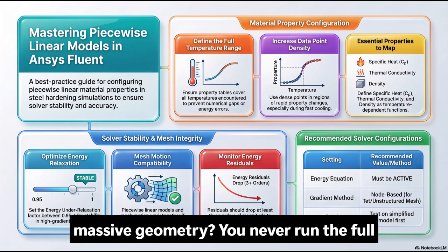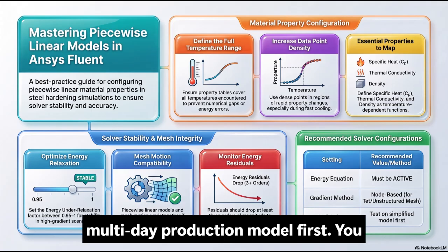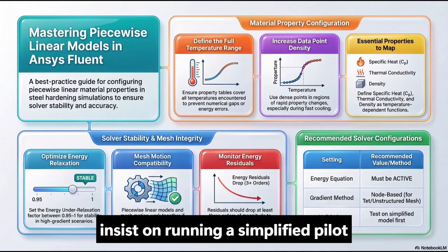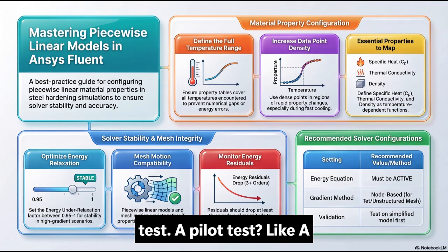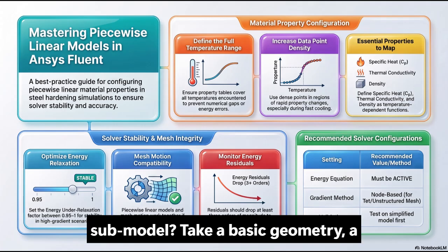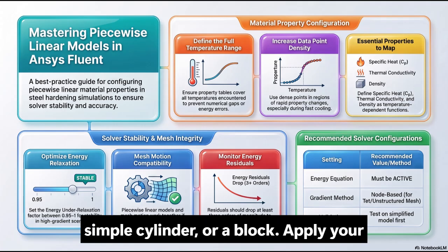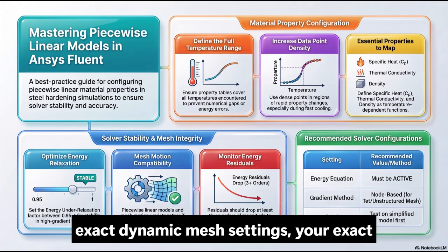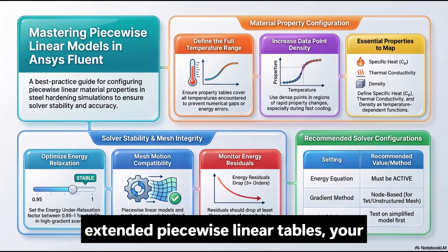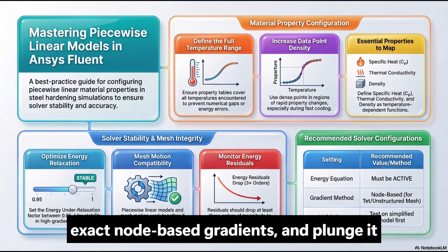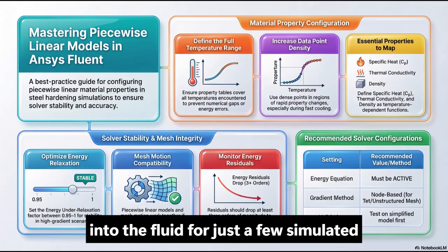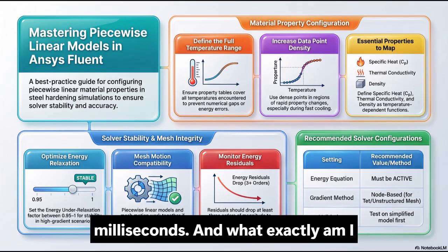You never run the full multi-day production model first. You insist on running a simplified pilot test. A pilot test? Like a submodel? Take a basic geometry, a simple cylinder or a block. Apply your exact dynamic mesh settings, your exact extended piecewise linear tables, your exact node-based gradients, and plunge it into the fluid for just a few simulated milliseconds.